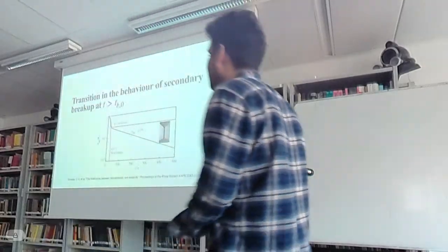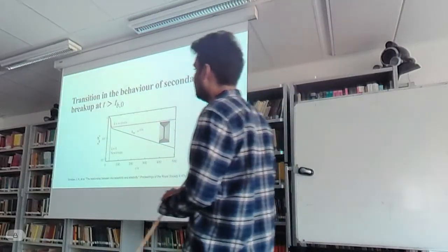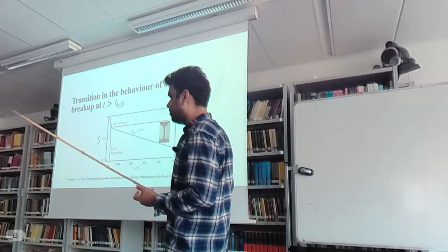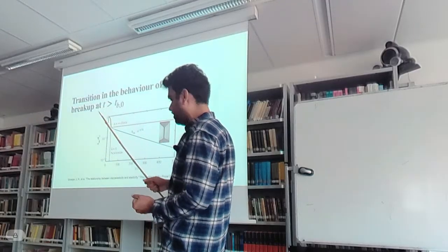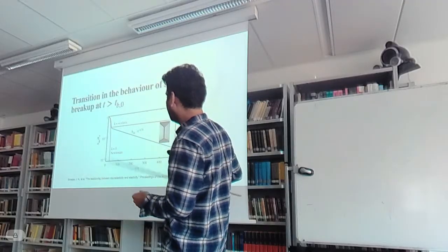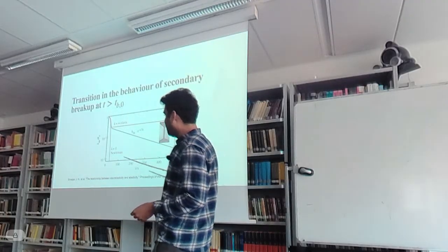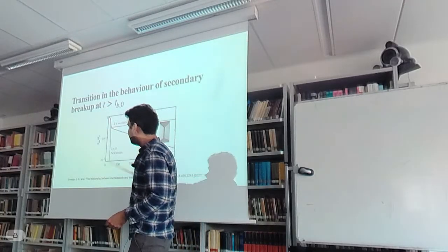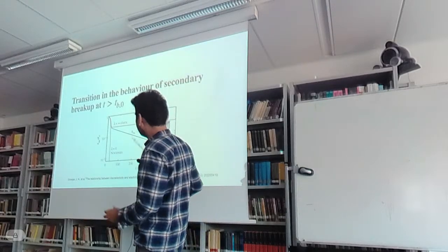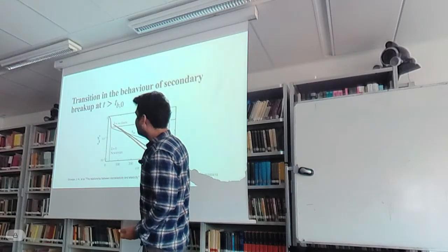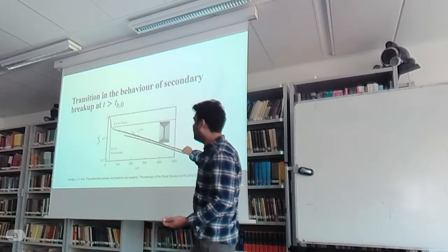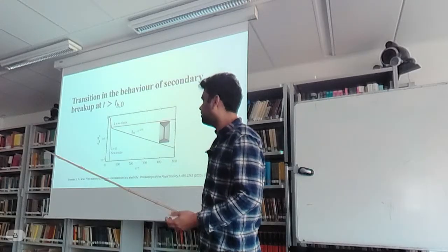And now I'll talk about the last phase of the jet, which is the breakup. So this is a problem similar to what people have studied in extensional rheology, that you take two plates and you pull them apart and you look at the bridge that is formed. For a Newtonian case, you will have a finite time singularity that breaks up this ligament. For a fully elastic case, you will always reach a certain height constant, and in case of a viscoelastic fluid, you have this power law.